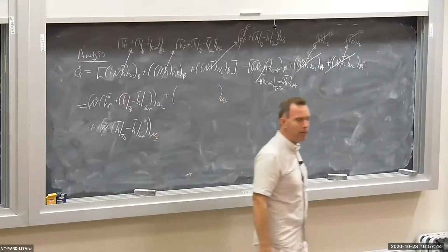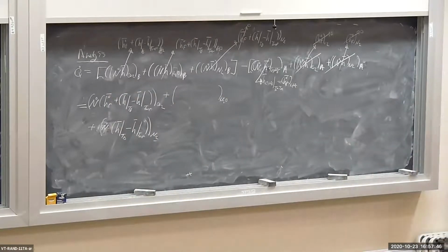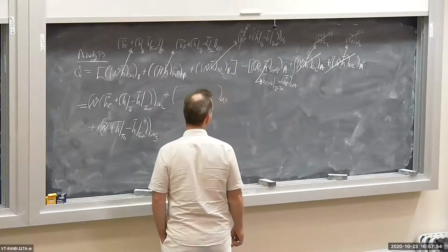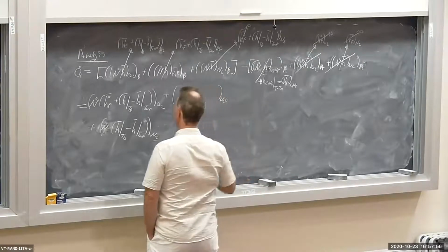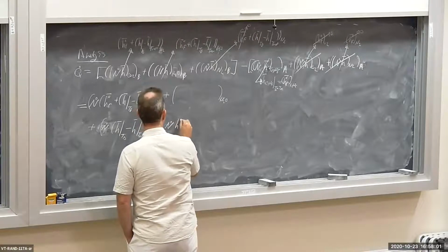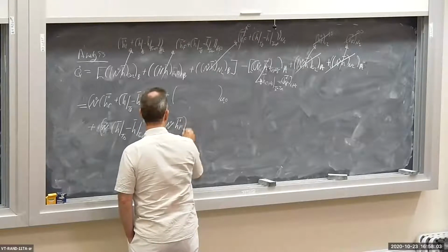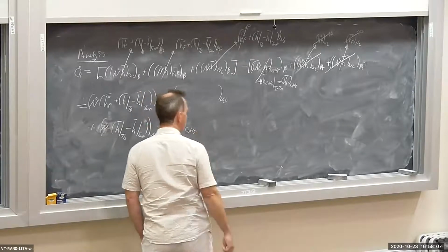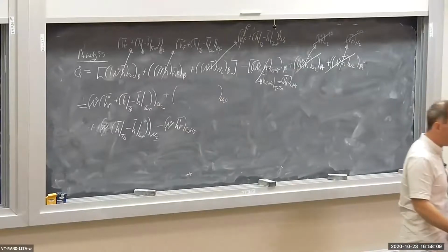Okay, that's the outlet enthalpy of the nitrogen term. And then I've got the last term here, which is the enthalpy of formation, or the specific enthalpy for the fuel. That's right here. So I get minus N dot enthalpy of formation, and this is for the propane, okay?